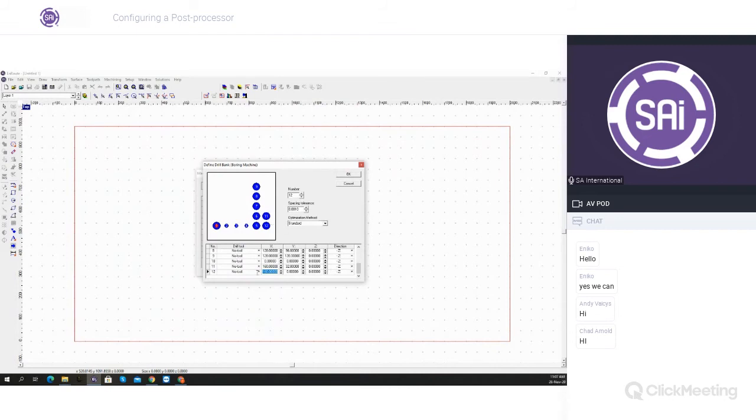And as you can see here, you can also define the direction of the drills. So all of these drills are going to drill into the Z negative. But for this one, for example, we could position it into the Y positive and the Y negative. So this would mean that the machine has an aggregate to drill into the sides of the material.